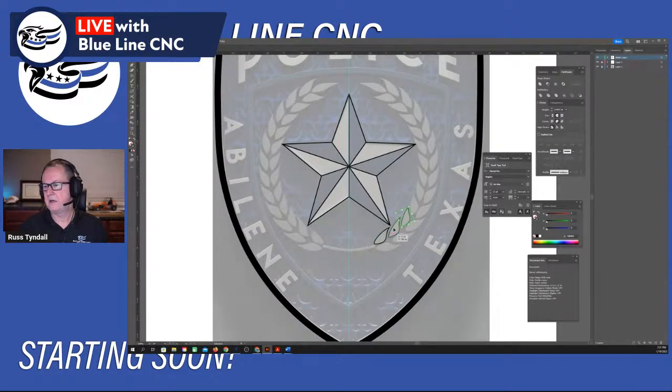And then once we have one side completed, say this right side, it's just a matter of grouping them all. In this case, we're going to hold down and select them all with Shift and the mouse button. And then we're going to hit Control G on the keyboard. And I think in Vectric, it's just, what is it? I think it's just G, but it's Control G in Adobe Illustrator.